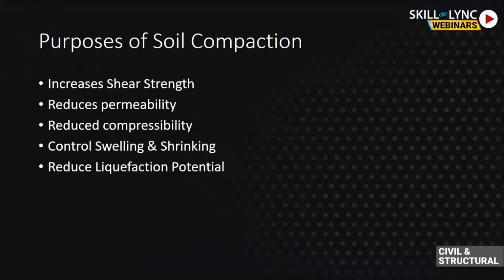Reducing permeability inhibits the soil's ability to absorb water and therefore reduces the tendency to expand, shrink, and potentially liquefy. And reducing compressibility also means that larger loads can be applied to the compacted soil since it will produce smaller settlements.